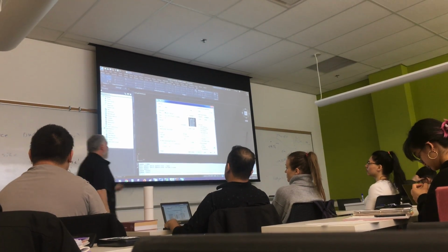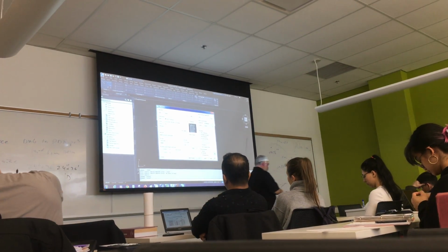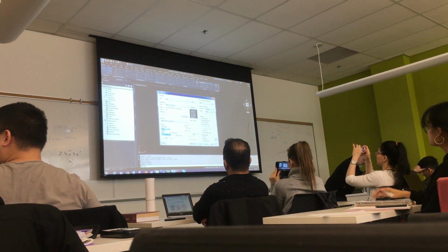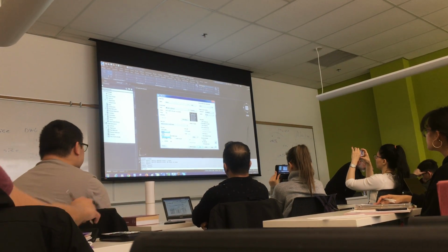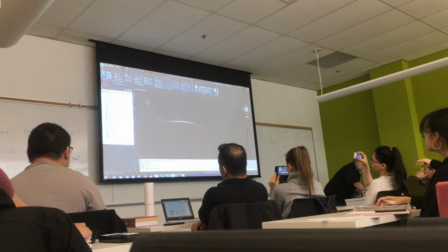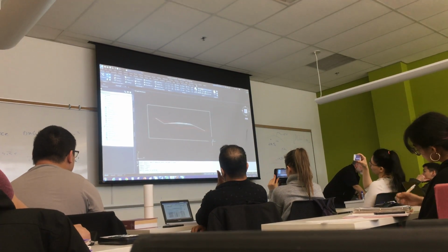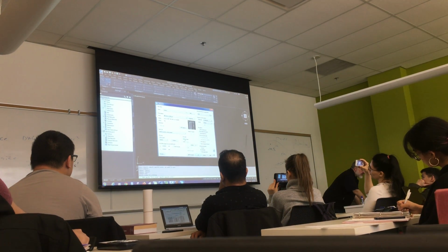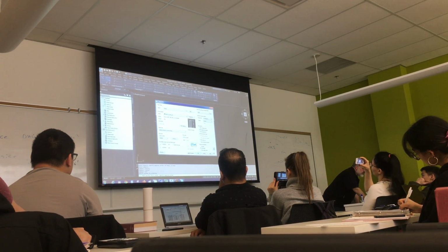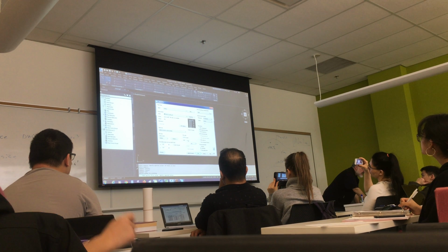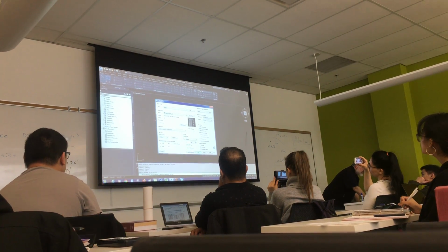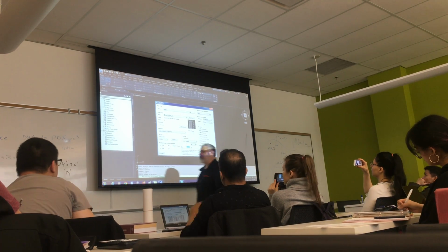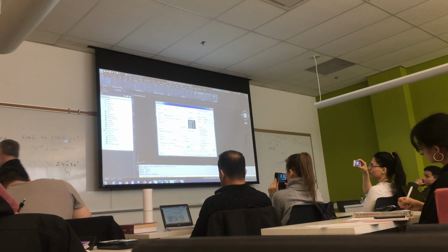The next thing you want to look at is the plot area. Use a window. You could use extents, but use a window. So you grab the whole thing, make sure everything's visible, including all the text and the dimensions and so on. And once you do that, for scale, you have to do this in millimeters. It can't be fit. We want to plot it 1 to 100. So to plot it 1 to 100, there's some funny business going on. So, plot scale.